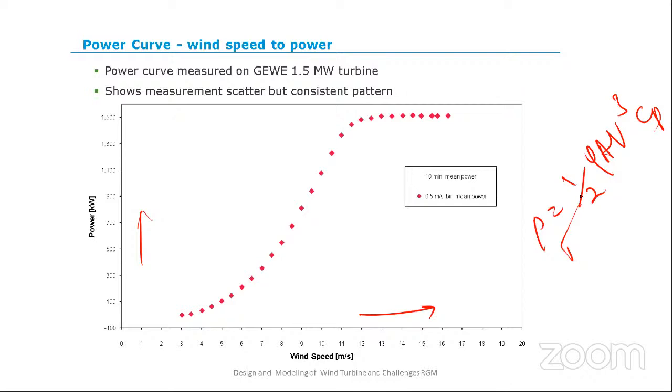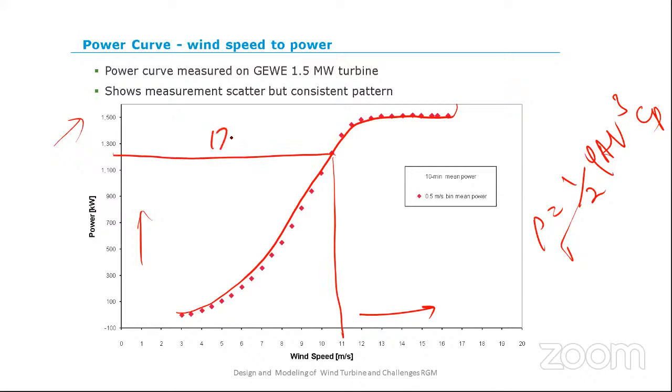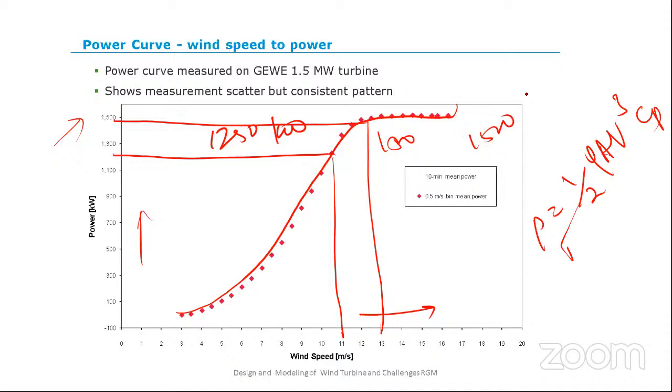So now, the power available in the wind. This is then the power, how much it's going to generate. This is the 1500 kilowatt turbine. How will it generate for each wind speed? Now I have designed at 11 meters per second, my turbine can generate 1250 kilowatt. And in case it increases to 13 meters per second, my turbine can generate 1500 kilowatt. Right.